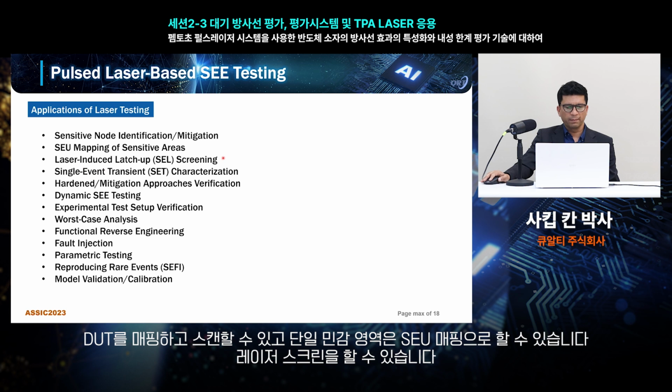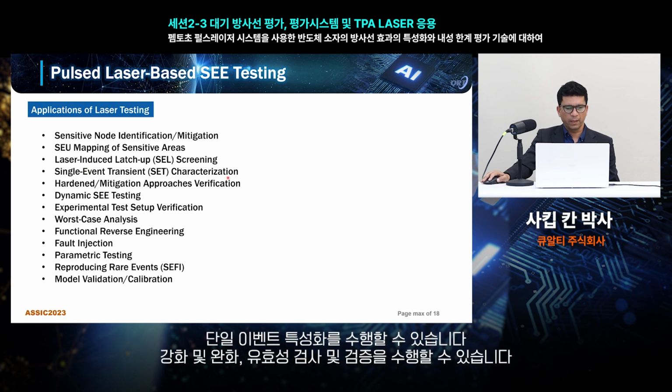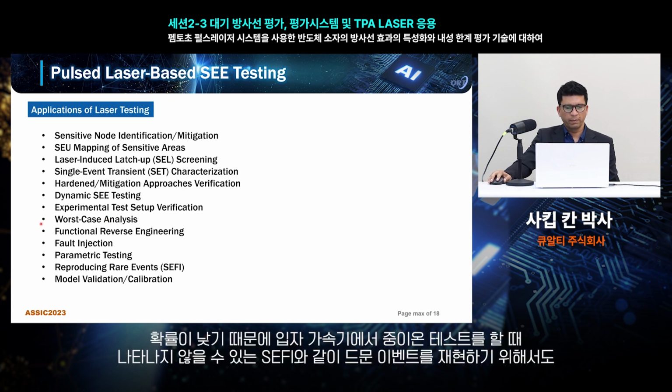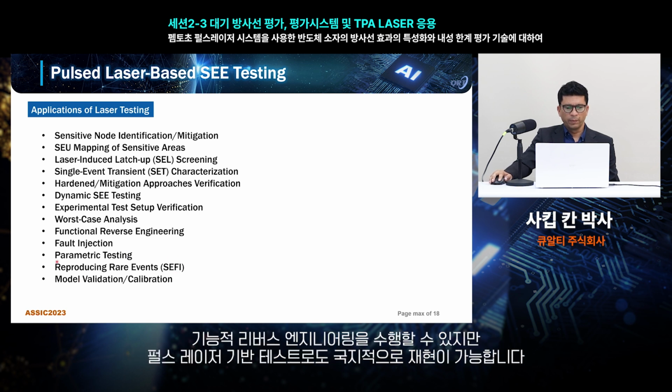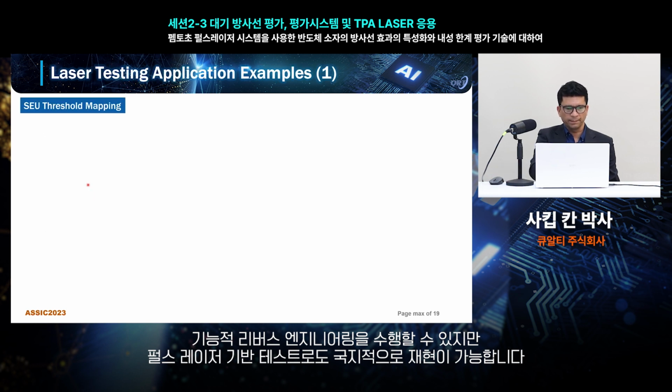Latch-up screening can be performed. Single event characterization can be performed. Hardening and mitigation validation and verification could be performed. Functional reverse engineering can be performed, and we can use it to reproduce rare events like SEFI, which might not be manifested during the heavy ion testing at particle accelerators because of their low probability, but they can be reproduced as well as localized using pulse laser based testing.